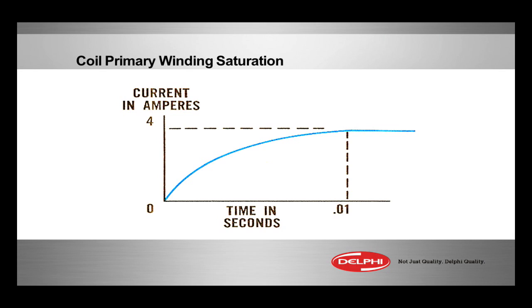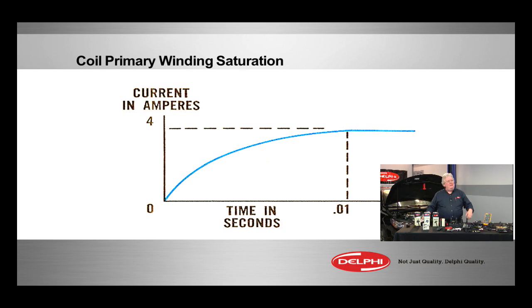If you use an amp clamp and any kind of a scope, let's say it's built into your Modis, your Verus, whatever you have, maybe you've got a 4-channel Pico scope like I've got, it all works the same. It will build up slowly. That ramp up is normal. If we don't see a ramp up, if we just see that coil turn on, or the transistor turn the coil on like this and turn off abruptly, that turn on abruptly means it's not really a coil. It's probably a short circuit, maybe something else besides the coil there across there.